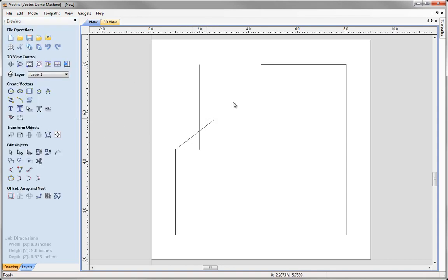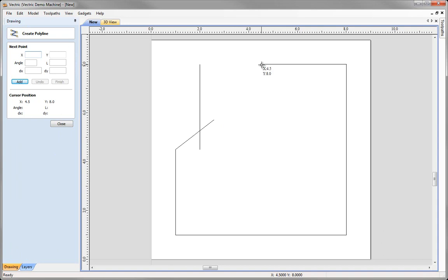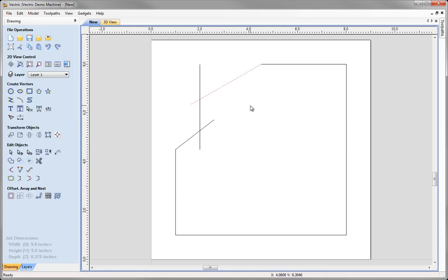So we'll close this now, and then I'm going to create another line snapping up to here. So we're going to come back into the draw polyline tool. I'm going to click on this end, and this time I want it to be at 30 degrees. Now if you remember, we've got the snapping set to 15-degree increments, so as we move the cursor you can see if I go slowly then it automatically snaps 15, 30, 45, so I can come over here and just move until I get to 30, make sure it's overlapping past the end of this line, and as long as I see those values next to the cursor then I know when I click that that will have snapped and be at a 30-degree angle. Again, if I'm happy with that, I can right mouse click to exit that function.